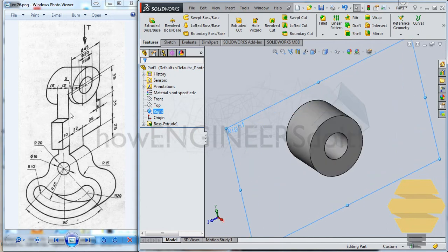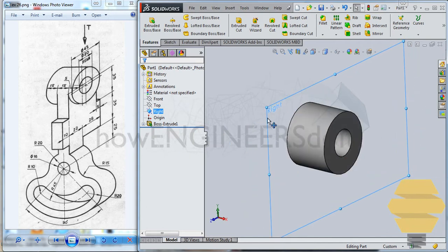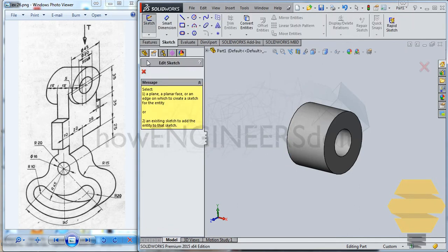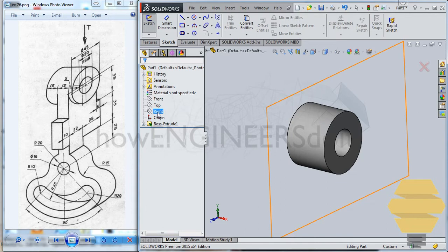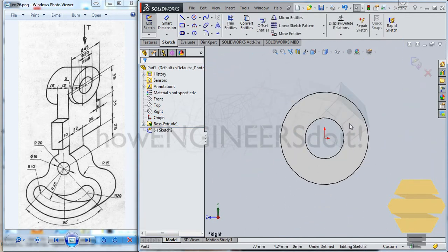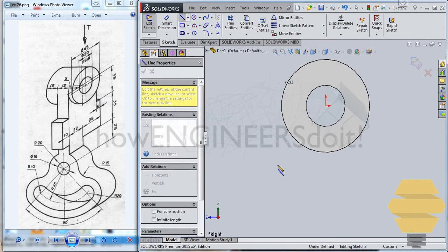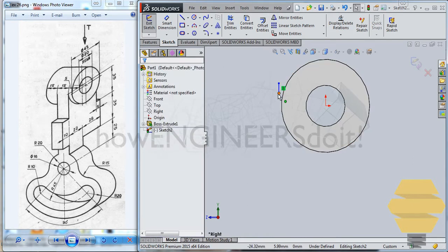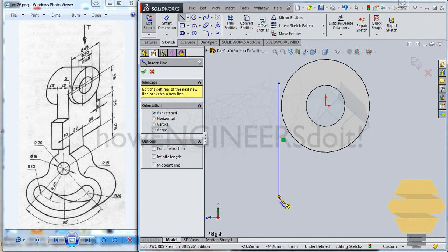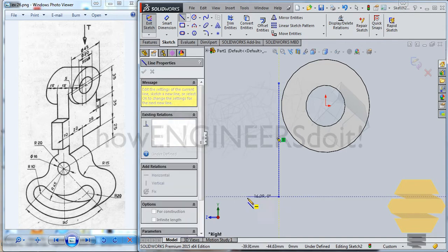So let's go ahead and create these portions. To do that, let's click on the ZX plane. I'll go to Sketch and click on the ZX plane, zoom out a little bit, and use the control key to place it the way you feel comfortable to continue with the sketching. We'll go for the line and simply draw a vertical line here. Every time you create a line in the beginning, it creates a cluster of lines. It doesn't matter, you can fix it really easily.